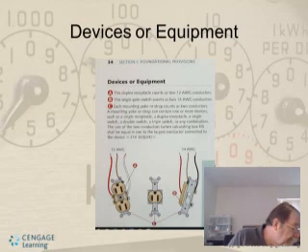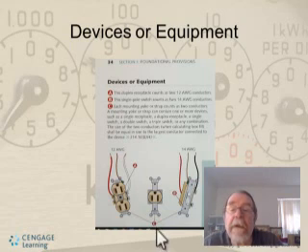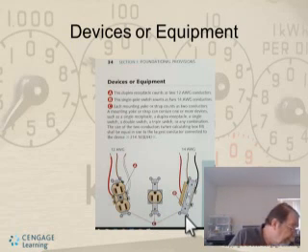Now each mounting yoke or strap counts as 2 conductors. That's number C. So you've got 2 conductors there. They're taking up volume in the box.